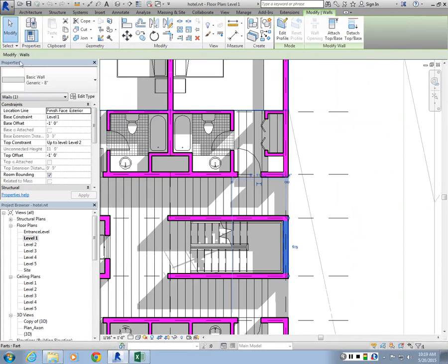So when you go to the properties and click on this drop-down menu, you can see all the loaded wall variations of this family. So these are all similar objects. They can be structural, they could be layered, they could be complex, and they basically have specific type features.